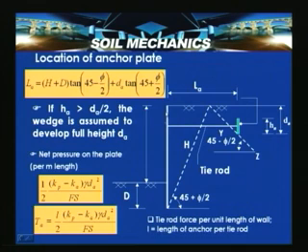So, if this is the wall cross section and this is the anchor tie rod, and let us say that this is a plate which is located having a depth HA, anchor plate, and DA is the depth of this tip of the anchor plate from the ground surface, LA is the length of this location of the anchor plate from the inner face of the wall. Now, in this case this particular zone is active zone and this particular zone is passive zone, and this particular zone is again passive zone and this particular zone is active.